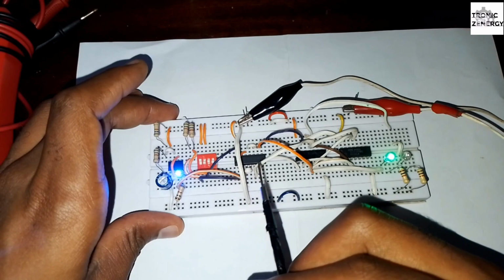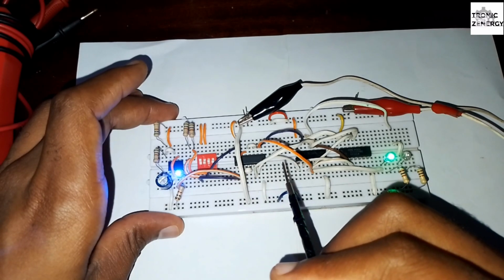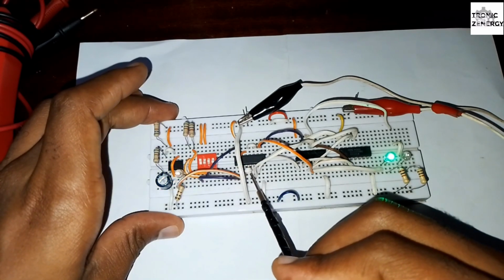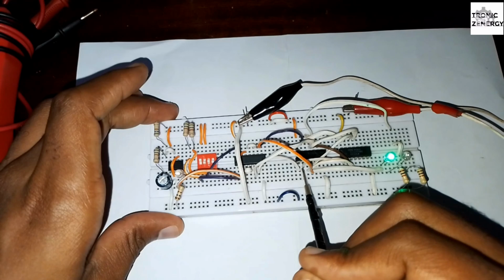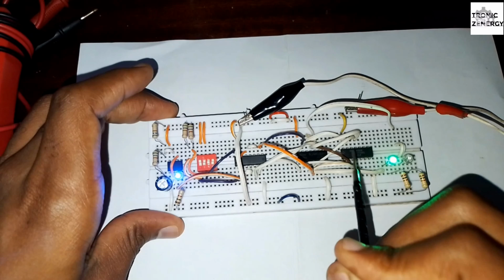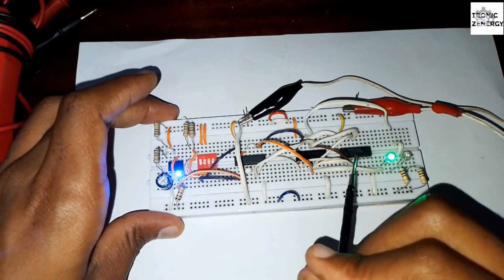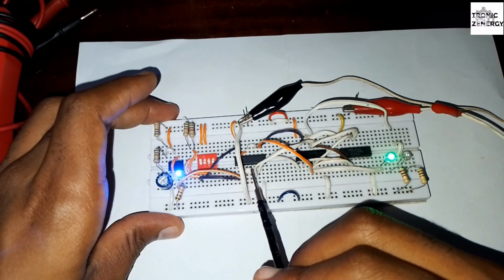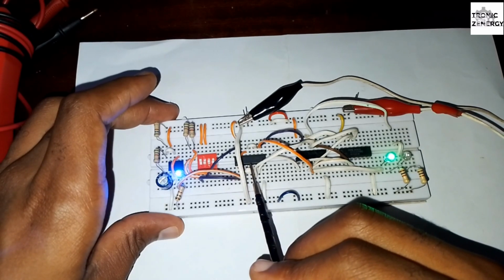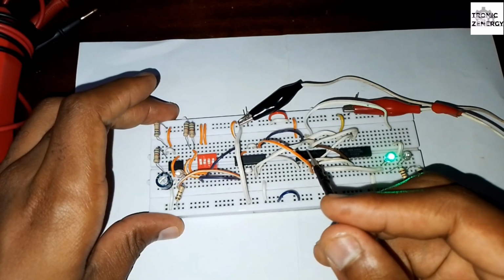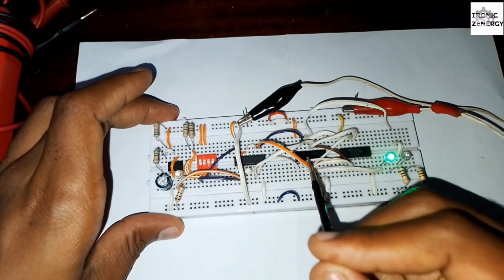Then here we have the circuit that is controlling the LED. So the first one is an AND gate, the middle one is a NOT gate, and the last one is another AND gate. I'm using two AND gate ICs, using all of the AND gates, because these are two-input AND gates and I'm making them three-input. Then I invert that output at this NOT gate to make them a NAND gate.